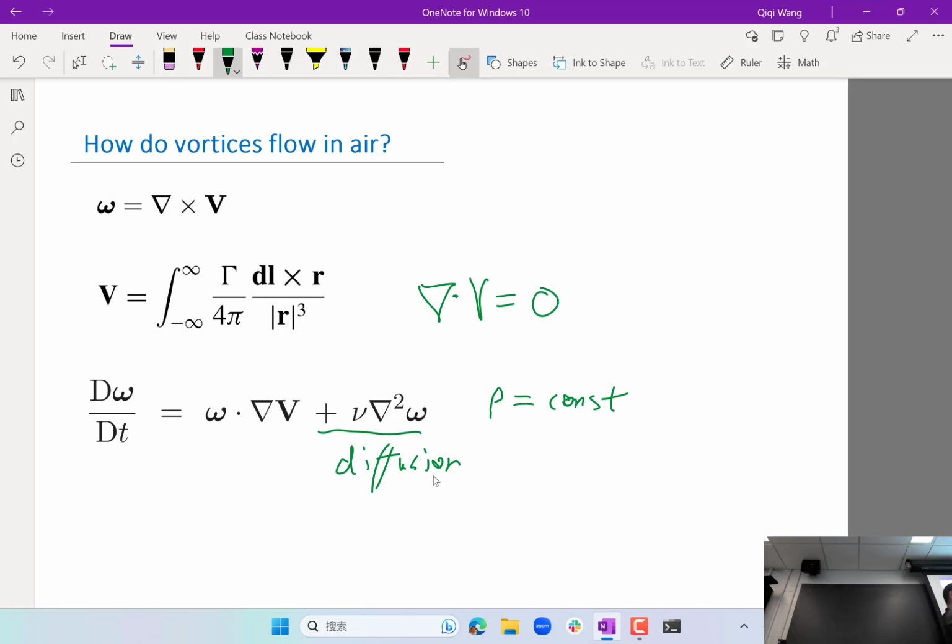Yes? So from there you're saying that if you have incompressible flow, there's no way you can generate a vortex? Yes, that's true, except on the solid boundaries. The velocity on the solid boundary has to be zero, right? So if you have a non-zero velocity right next to the boundary, then there is vorticity by definition. Even if you have a zero thickness boundary layer, then you have infinitely strong shear, like infinitely strong vorticity here in the boundary.